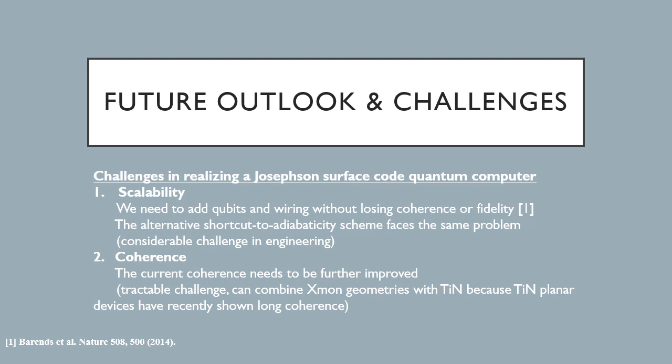Another challenge is the need to improve coherence. Fortunately, this is a tractable challenge because of the recently discovered coherence property of titanium nitride. Combining Xmon geometries with titanium nitride is a realistic idea and may lead to a longer coherence in the future.